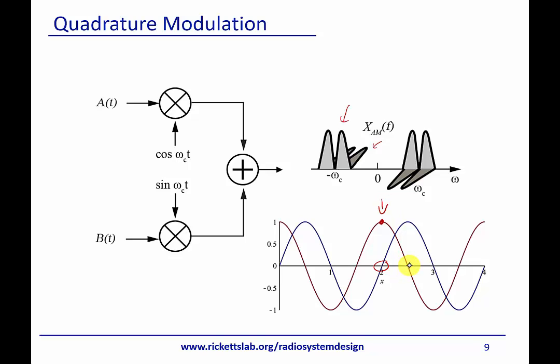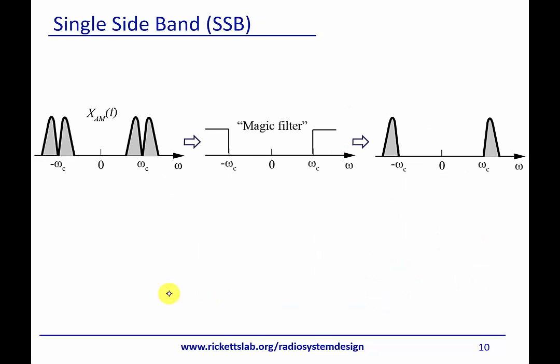So that means any signal I receive at this time is just from that cosine component. Just like if I go to this point in time and look at the signal I'd receive, I would just be seeing the sine component. So you can see in an easy fashion here that because these are phase shifted and one is 0 when the other is not, and vice versa, it's easy to see that I could transmit a sine and a cosine and get different values of the amplitude from the received signals. I think that helps give a little bit of intuition.